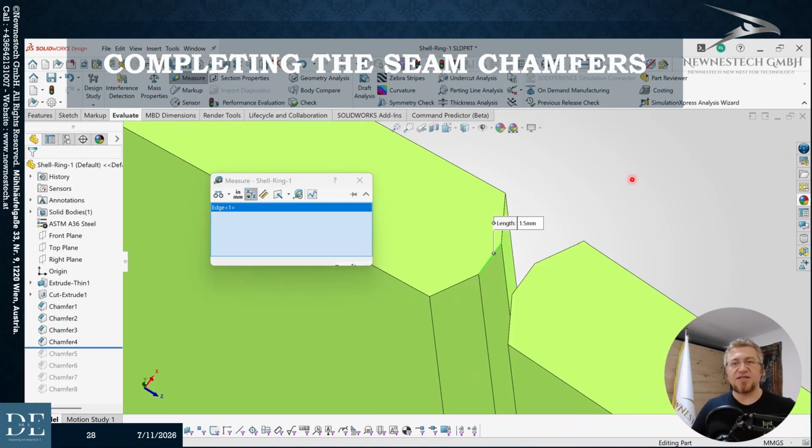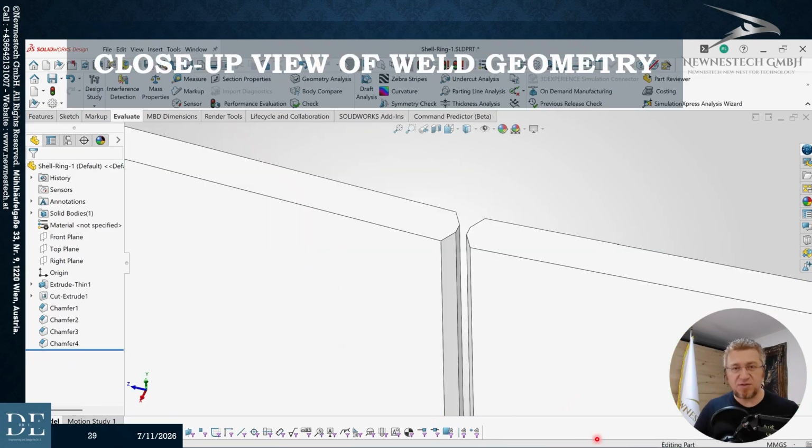We repeat this identical chamfer command on the remaining vertical edges of the gap. Since we have both internal and external weld prep considerations for full penetration, we apply this to all four vertical boundary lines. This close-up shot gives you an excellent visualization of how our joint preparation looks in 3D. This pristine 60-degree V-groove is exactly what the fabricators will see on the shop floor before initiating the MIG welding process.